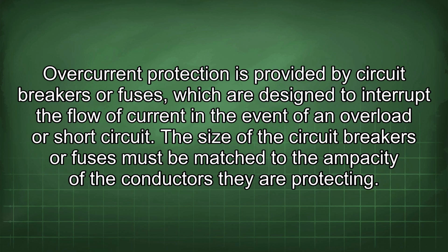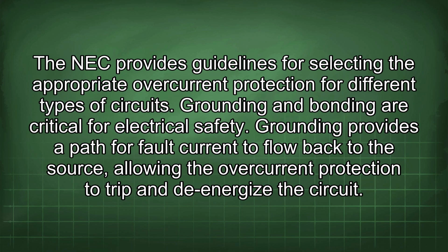The size of the circuit breakers or fuses must be matched to the ampacity of the conductors they are protecting. The NEC provides guidelines for selecting the appropriate overcurrent protection for different types of circuits.